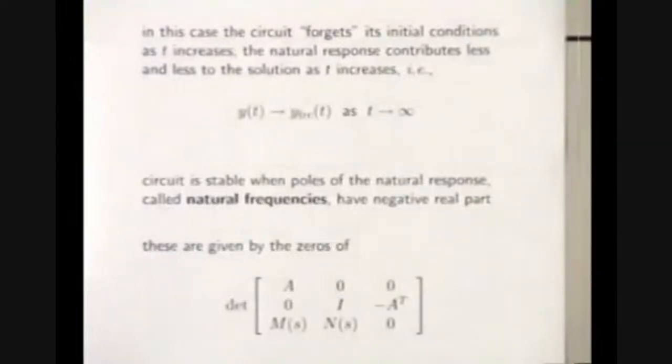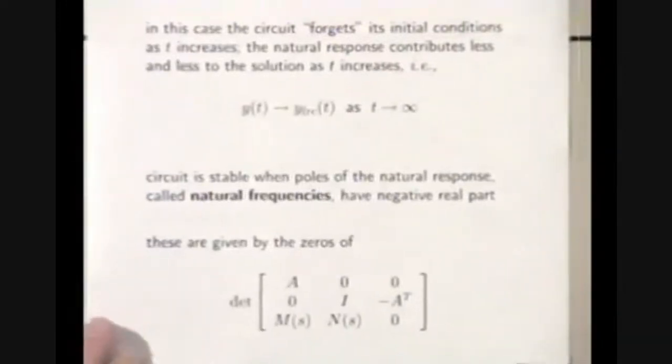And in fact, it's so common that often people don't even worry so much about the effects of initial conditions. And then people say, well, why don't you worry about it? And you say, well, I'm assuming they're zero. And someone says, well, is it true that they're zero? And you say, no. But whatever they were, for this circuit, their effect vanished within 12 microseconds. So after 12 microseconds, for all practical purposes, the initial conditions might as well have been zero. So this is sort of the idea. We won't go into great detail about this, but that's sort of the idea.